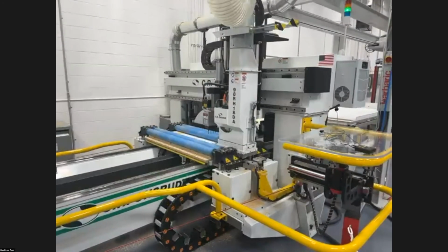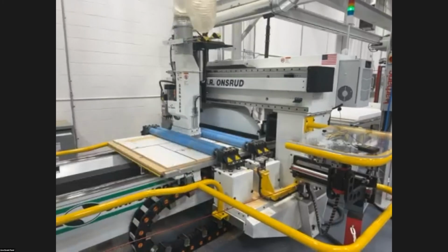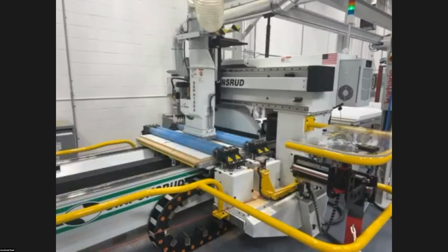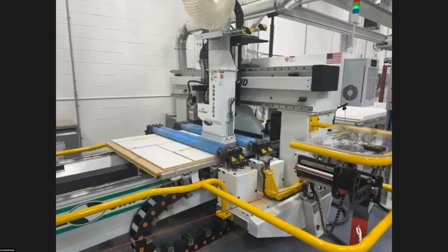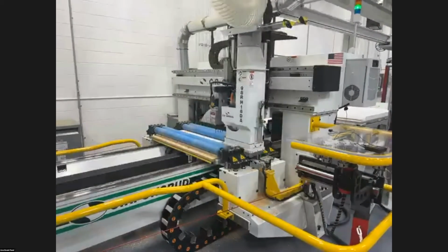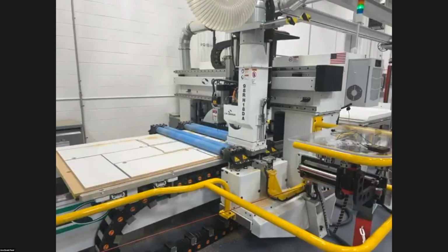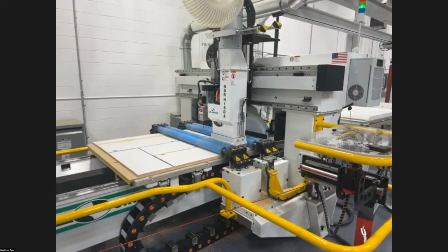You probably also are wondering what the rollers are on the table. We have clients that cut warped material, such as plywood. Well, the rollers help hold the material flat during the cutting process, warped material. As well as we have clients that cut stacked material, multiple layers of a material. So the vacuum table will hold the bottom sheet, and then the rollers will hold the sheets that are stacked on top of that.